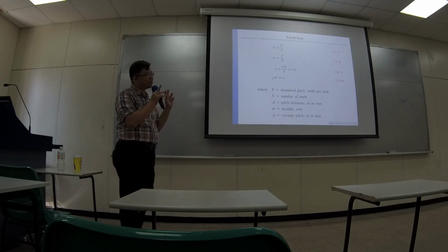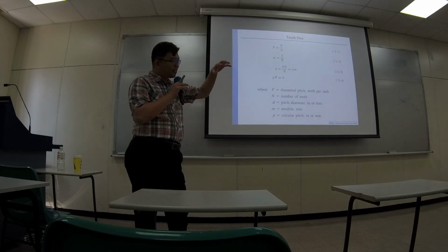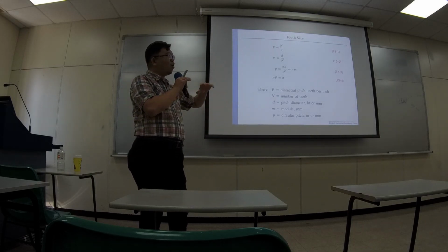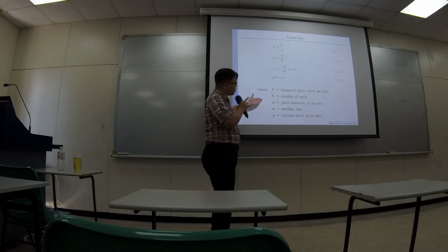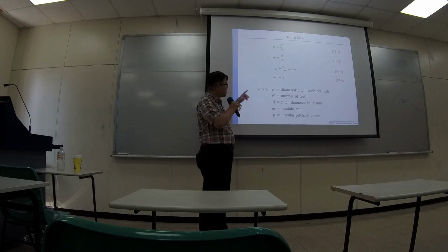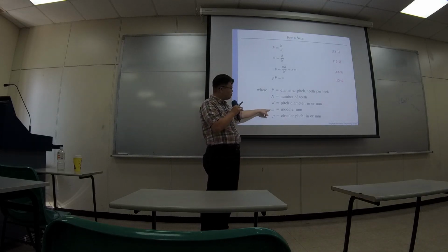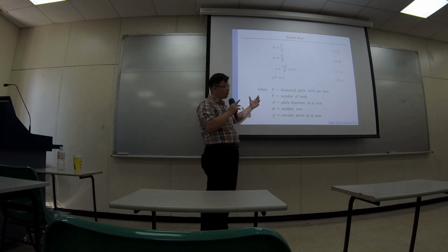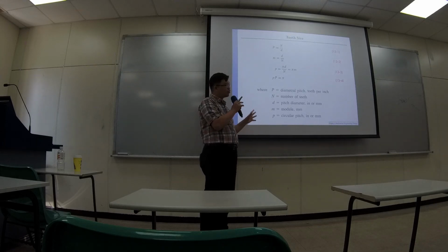Okay. It's very difficult for the manufacturer to prepare the cutter in all kinds of dimensions. That's why they have these calculations and claim, okay, now I am designing a gear in a module number of 1 or 1.5 or some number. So they can prepare a certain set of cutters or tools to manufacture those.